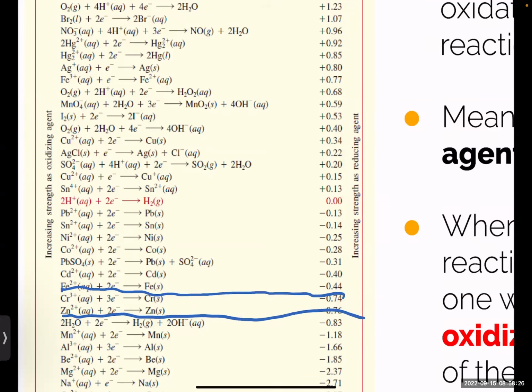Well, if the cost supports it, you can also coat your iron with some other metals too, right? You can also coat with aluminum, because aluminum also has a lower E° than iron. You can also coat your iron surface with aluminum, same thing. You can also coat your iron with magnesium, same thing, because it rusts away from the surface before iron does. Okay, so that protects your iron structure.